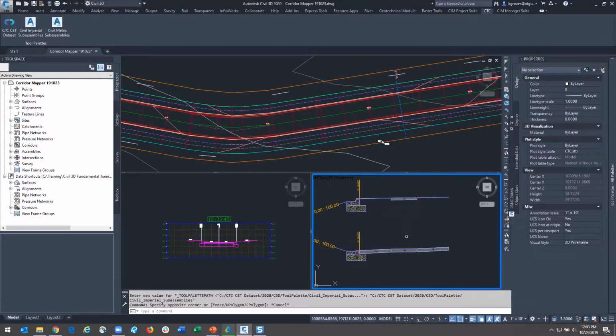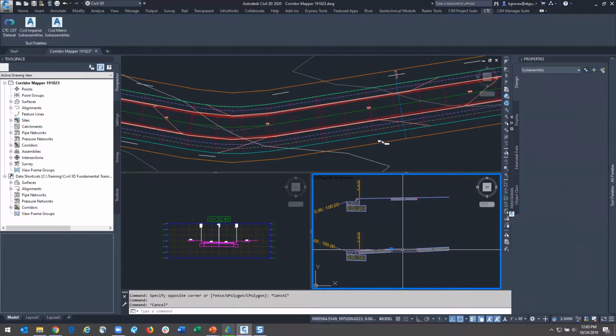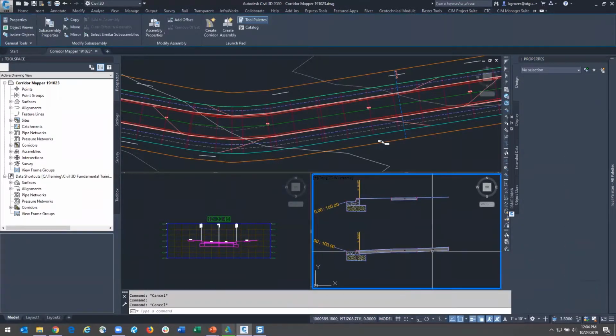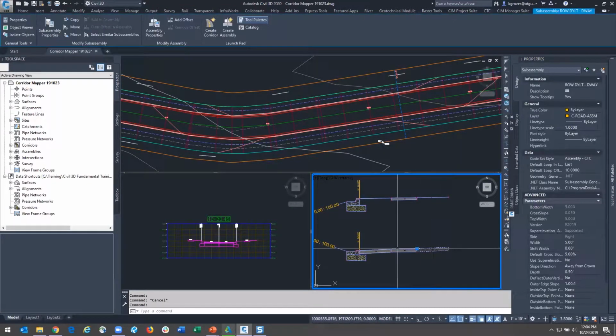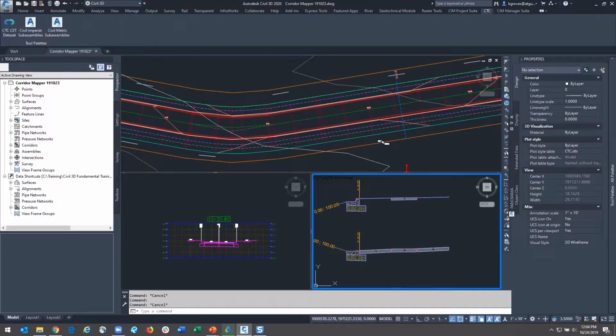So this is a little bit more of a situation where we've got a sidewalk. When I need to drive over, obviously I'm going to have some pavement. I'm going to have my sidewalk section, and then I'm going to have some additional pavement that's going to tie back into some sort of targetable object. In my case today, we'll be using the right-of-way.